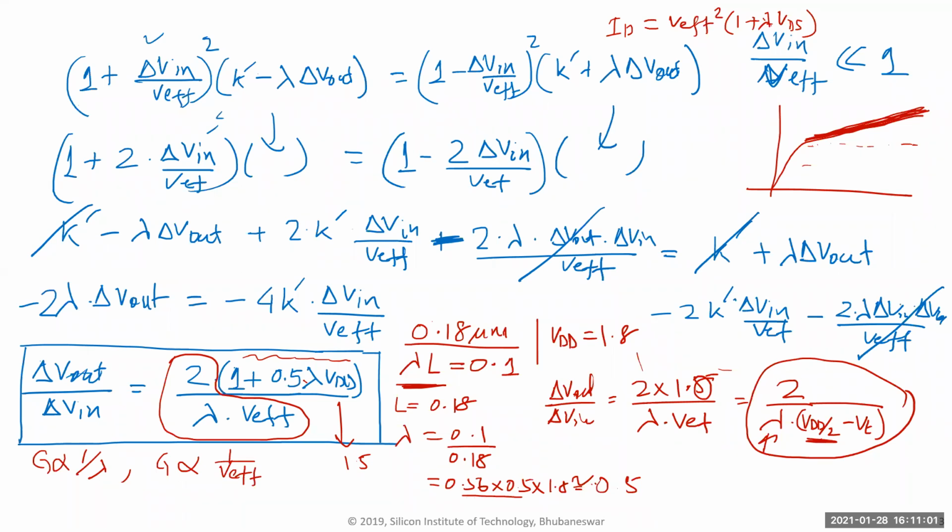your transistors are way faster than that, then you can operate it in subthreshold, because for subthreshold, you make your transistor size huge. Sometimes they're really big, which means that the CGS capacitor will be big. So whatever is driving it slows down. But if your signal is slow to begin with, just make it huge. If you don't care about the area that much, make it huge, and then your current required will be a lot less. So I'll show you a parameter, gm over ID, and I'll show you how they vary and how much current you can save going from saturation to